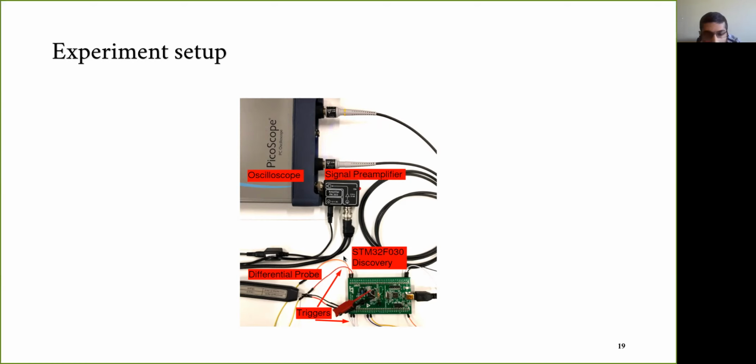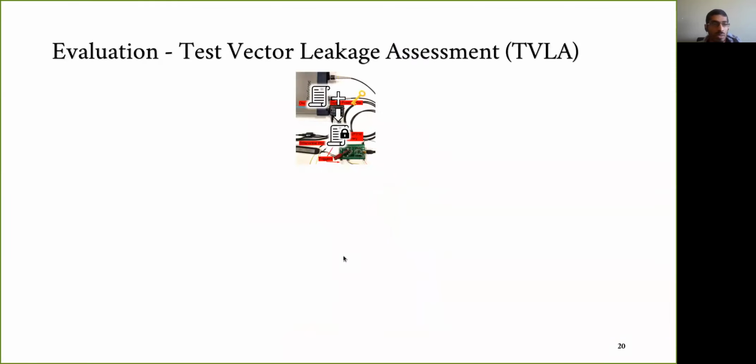I don't think you can see it, but there's a little resistor fitted in between the power rails of the CPU here. There's a little bit of damage we need to do to the circuit board to do this, but for cheap boards it's not much of a deal. There are ways to measure things in a non-invasive way too, but we have opted to do it this way.